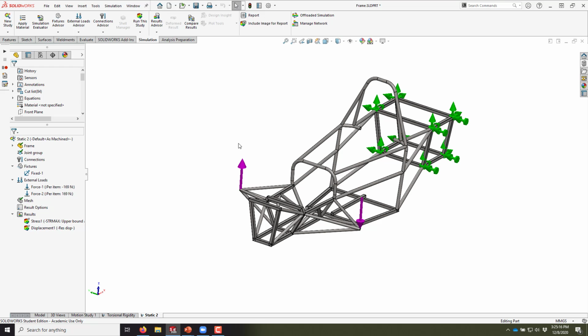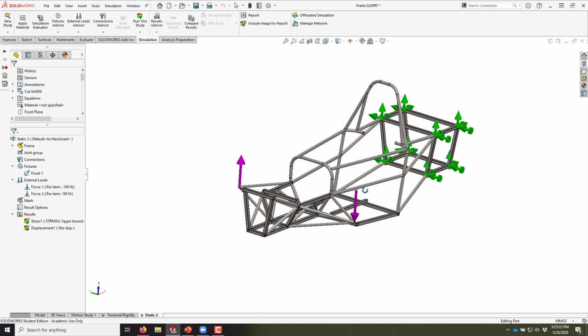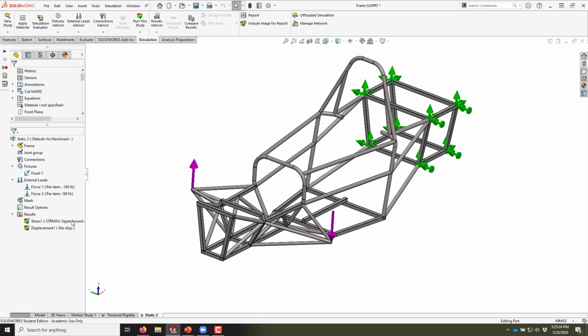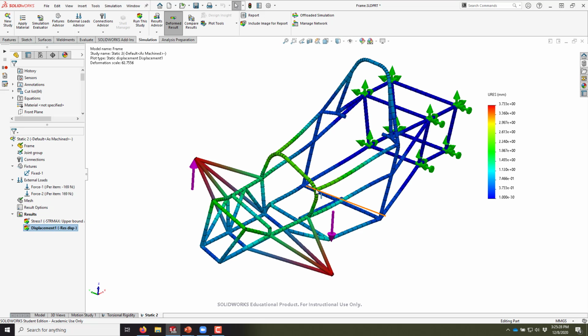Okay, so if you use your SOLIDWORKS structural member tool, the weldments tools in SOLIDWORKS, it'll make running these structural analyses a lot easier for you. Now you will lose a little bit of that detail. Like if you did want to really look at stresses on a weld, then that becomes a bit more of a process. Okay, and we'll have to direct you to some tutorials on that. But at a basic level like this, real quick and easy to set up.